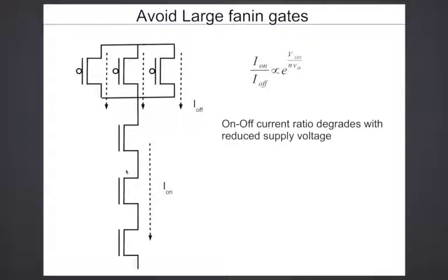The point being raised is, why not limit the pull-up current by putting a diode connected PMOS? Of course, you can play that game. In fact, that is what is done in the level converter, where the current in the PMOS was reduced by putting a diode connected PMOS. So you can do all those games, but you have to carefully engineer some of those things.